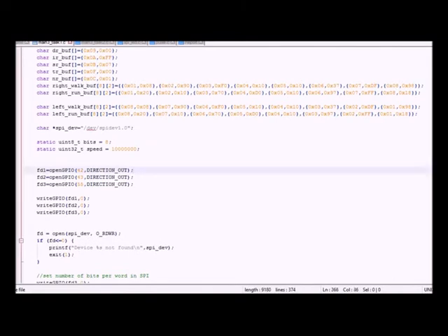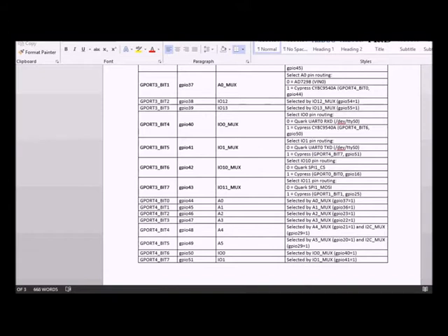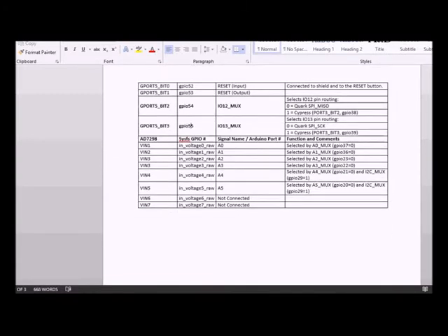To configure the SPI bus on the Galileo, we need to configure 3 pins: 42, 43 and 55. Let's look in detail at the pin configurations. When you look at 42, you make it low and the SPI1_CS pin is activated. You make GPIO 43 as 0. You make the SPI1_MOSI pin of the quark processor available, and you make GPIO 55 pin 0. It activates the SPI_SCK, or the clock pin.